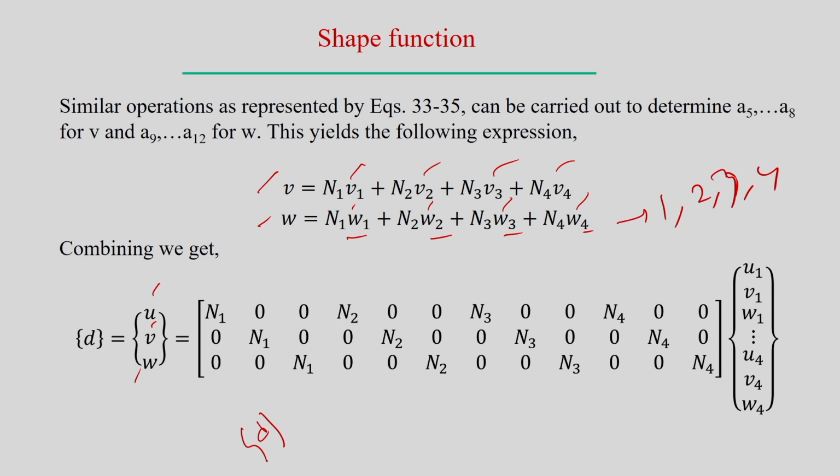So, therefore, this column vector represents u, v, w, the general displacement field. Then, in terms of the shape function, we put n1, n2, n3; it is simply representing it in matrix form, so that the system of equations can be represented in matrix form. We know that u, here you can also write, u equal to n1 u1 plus n2 u2 plus n3 u3 plus n4 u4.